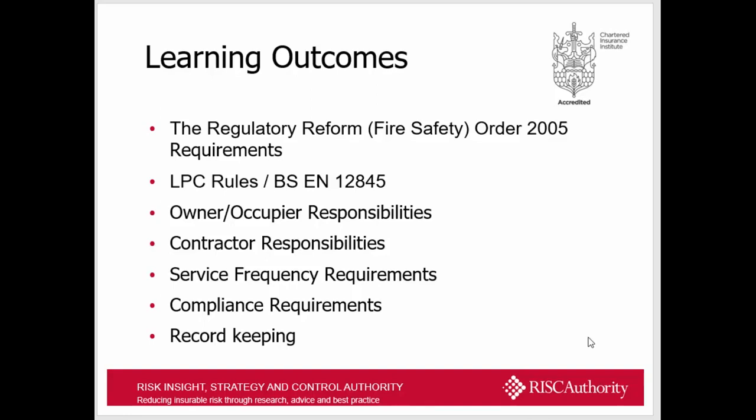The understanding between BS EN 12845 and the LPC rules: one is a life safety requirement, a minimum standard, and the other is more geared towards insurers' requirements for property protection and business continuity. The responsibilities for the owner-occupier, and the contractor responsibilities to provide the owner-occupier with a fully compliant service and maintenance regime. You now understand there are service and frequency requirements. If you do not have service and maintenance, it invalidates your certification under the schemes, and it may also have an effect on your insurance.